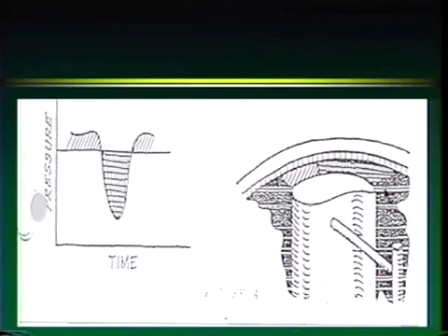Okay? Without this action, fibers would accumulate on the screen plate in milliseconds, and we would have blinding. And of course, we can't have blinding. So basically, it's like this foil is really saving our hides. Before we had these foils, we couldn't really do pressurized screening like we're doing now.